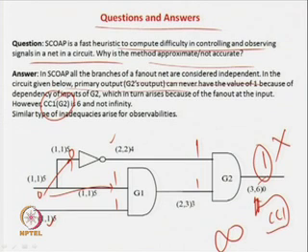But SCOAP will say that it has a finite level of difficulty, that is 6. That is not correct, because you can never get a 1 over here. So, stuck-at-0 fault testing at this point is impossible. But still SCOAP will say that you can test it, the difficulty level is 6, observability is 0, so it is very good, at the level of 6 you can test it. But it should tell you in an accurate way that the difficulty of getting a 1 over here is infinity, and that is why the stuck-at-0 fault cannot be tested, because of the contradiction I have said.